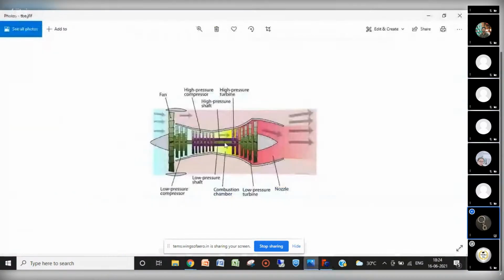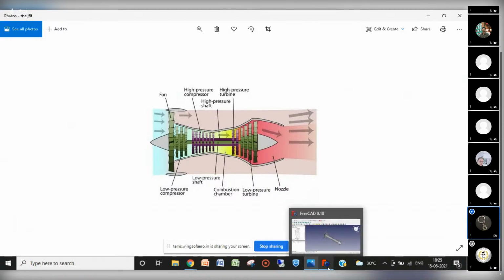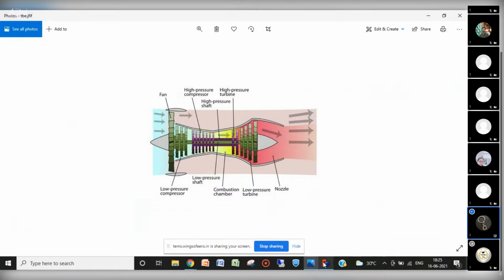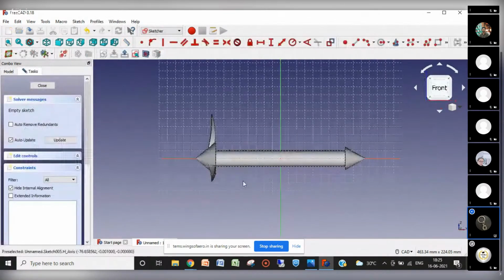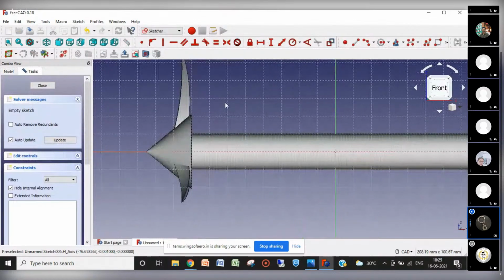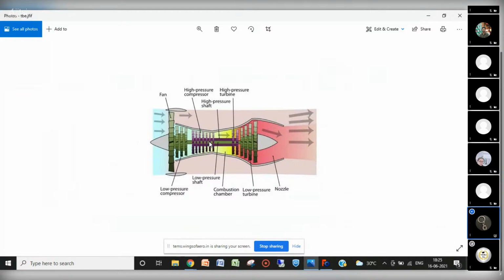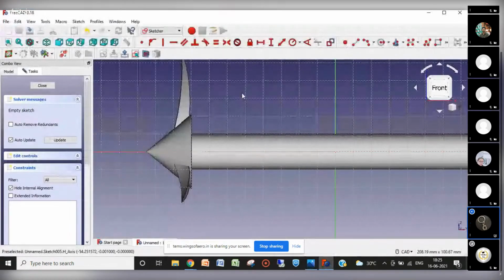Now we are left with our compressor and turbines and the covering of the engine. So let's start with our compressors. Compressor blades are not rotated, or you can say molded like the propeller blades. They are straight, so we can take our exact plane to make them and sketch it. Zoom in. Here we need our turbine plates. So need not to be 7, there can be 4, 3 and 4 would be there, 3 and 5 would be there, whatever you want to make.